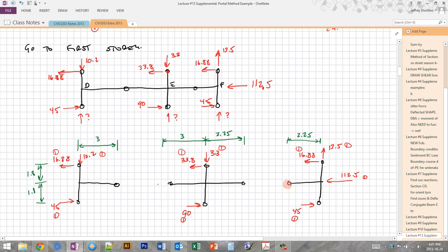So you see here on the right, we have 3 unknowns, 2 at this joint and 1 at this joint. So in order to find the vertical unknown at this location, at the lower right here, we're going to take moments about this pin right here. It's best if you can get used to doing this process without having to write it all out at once. But if you want to write it out on a scrap piece of paper just so that you get the directions right, that's not such a bad idea. But really we have to do this so many times in this process, finding the moment equilibrium, finding the vertical and horizontal equilibrium, that you really want to get to a point where you're very comfortable doing this pseudo in your head.